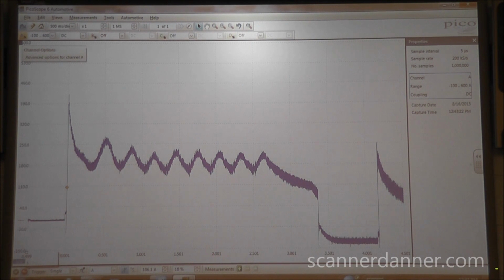That's kind of funny. So what this provides you is a method of stopping the scope when you're not near it. If you're working under the hood and maybe you're the one that's cranking and you need to hurry up, run over and hit the stop recording on the scope, you don't need to do that. Set it for a single.